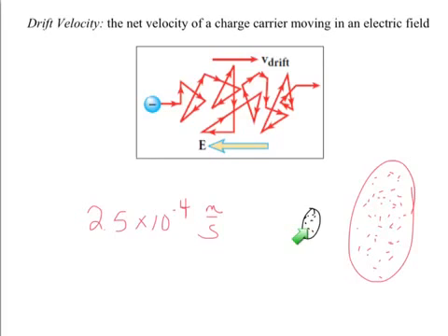Now, the next real question is, why isn't there a delay when you turn a switch on, but it immediately turns on, right? Wouldn't there be a noticeable quick delay there? And the answer is no, there's not. And the explanation has to do with what's called a charge carrier, as we've been saying. So charge carriers in wires, they're electrons. And the electrons, they're just supplied by the atoms of copper or whatever the material is made of in the wire.